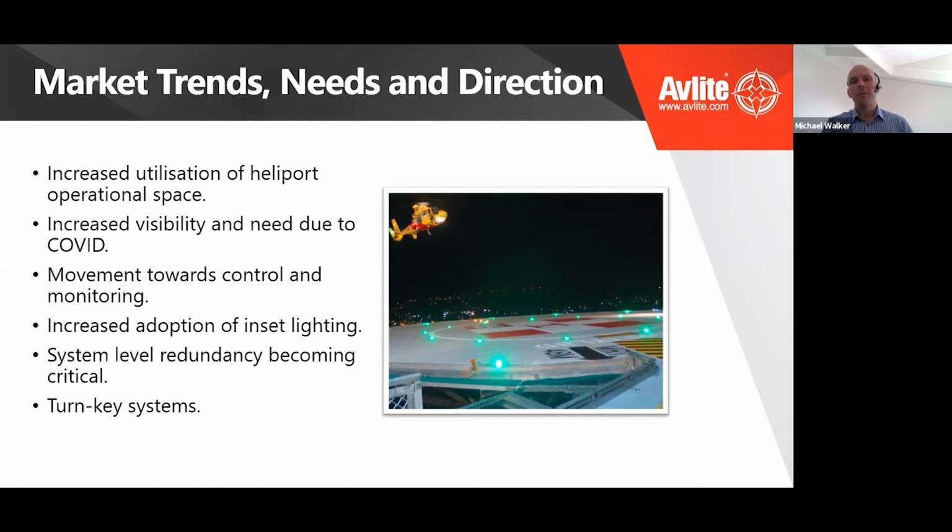The fourth is, certainly in my time, and Wade and Vicky will attest to that, we've seen a strong shift from what was once a prevalent elevated industry towards inset. As we've seen some of the specifications around the surface area of the heli deck, the helipad or the heli landing site, managing issues like dynamic rollover, etc., there's been a stronger need and identification for inset lighting to remove any and all hazards.